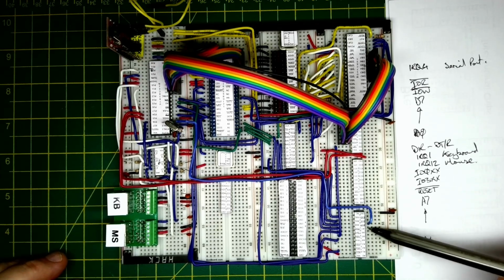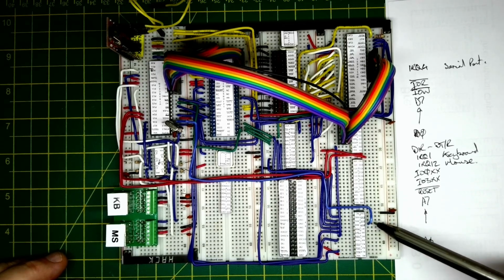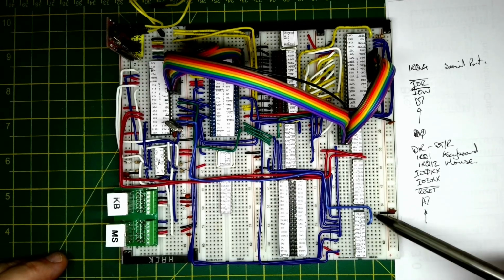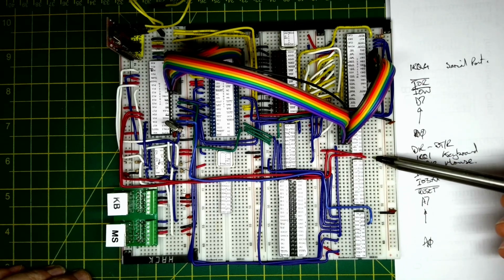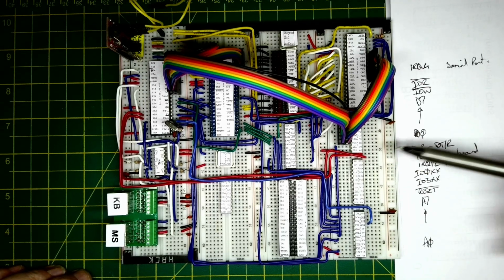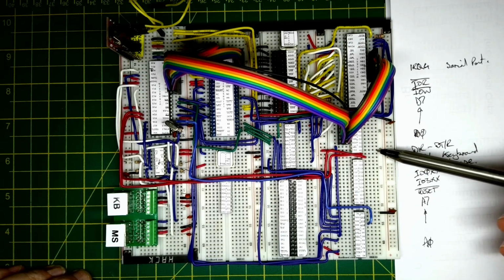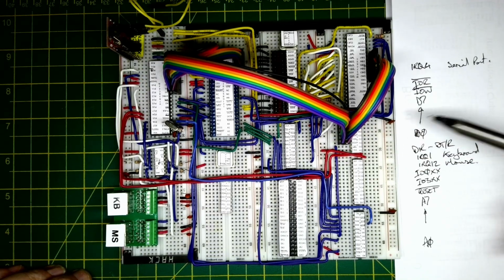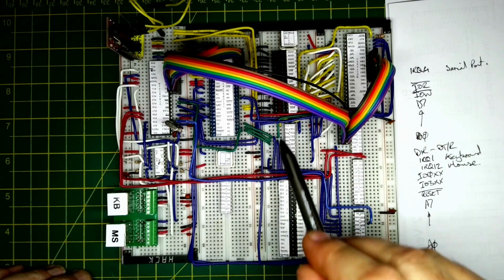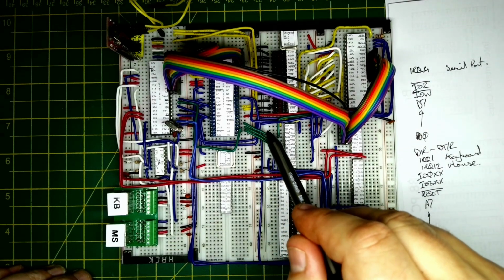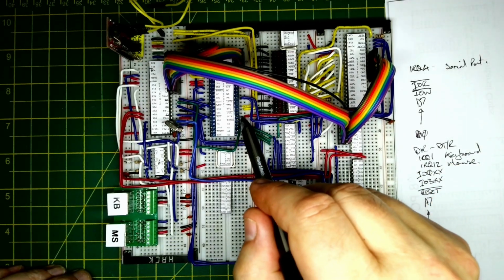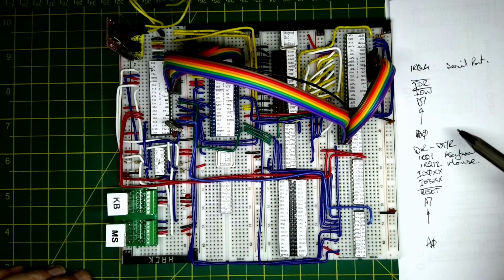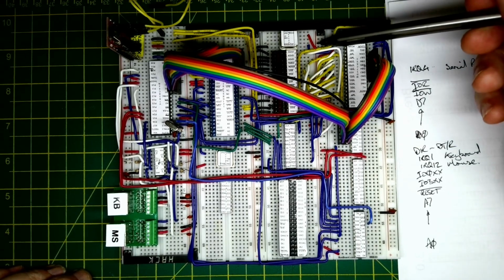So we've got A0 to A7, we've got the active low reset, the IO 3XX, IO 0XX, so those are like the decoders for some of the IO ranges. Nothing here. Then we've got IRQ12 for the mouse, IRQ1 for the keyboard, direction goes to DTR, then we've got D0 to D7, and then IO read and IO write need to go into these two sockets over here, and then IRQ4 is over here and comes out here, so we might just wire that straight into there, and then that should have everything wired in ready to go, and the power connector goes up here.